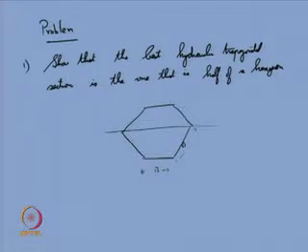So, this particular section, this portion, whatever is there, that is the best hydraulic trapezoidal section. How can you prove that? You have already seen what is the criteria for the best trapezoidal section. You can develop from there itself how the best hydraulic trapezoidal section is half of a hexagon. It can be proved. Just do that.